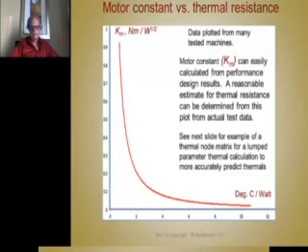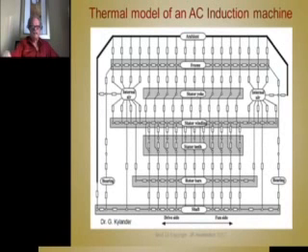And the other thing you could do, if you have a lot of motors in your company, you should make these measurements to develop your own history, and you could compare that with a rotor surface area and volume. This is a thermal model of an AC induction machine that was presented by Dr. Kylander. It's the same idea as Dave Staton's, but you can build a solver for this and calculate this.